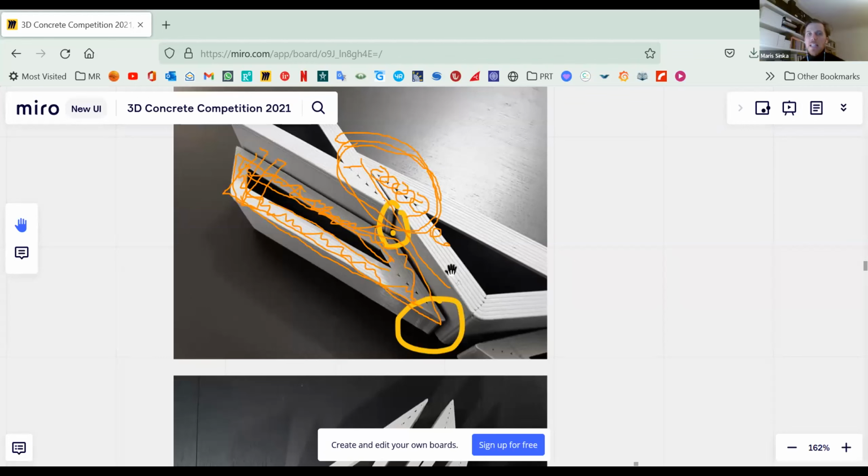As I said, I would suggest not drilling in this concrete afterwards. If you need to insert something, like a 90-degree angle where you can screw something inside, then let us put the angle on the surface and then print on top of it. Yeah, if it's possible. And then it would be perfectly inserted and perfectly well bonded with the concrete.